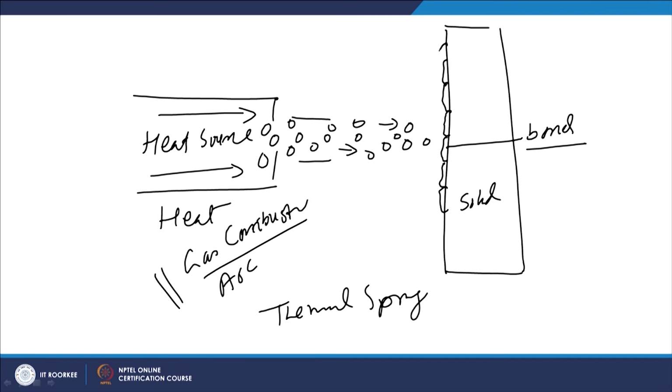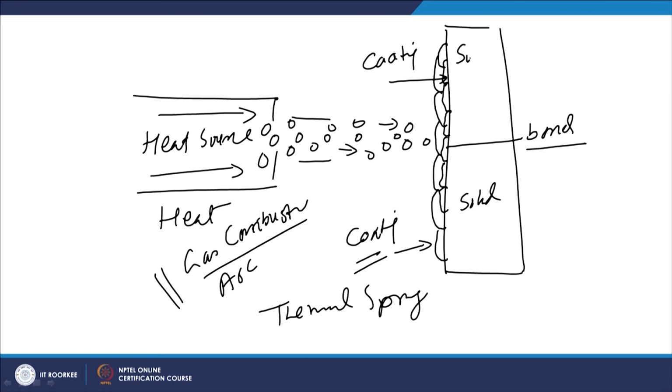So, eventually when we get sufficient thickness of the layer being developed, we get a coating of the required material on the substrate, and that is why bonding between the coating and the substrate becomes crucial, because there is no fusion of the substrate, and the molten or partially melted material impinges, gets flattened and solidifies.